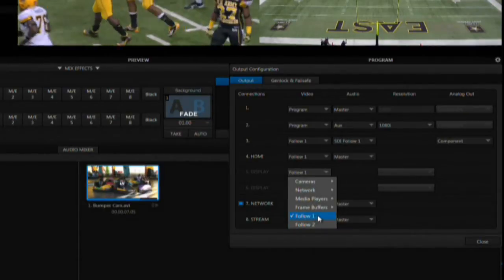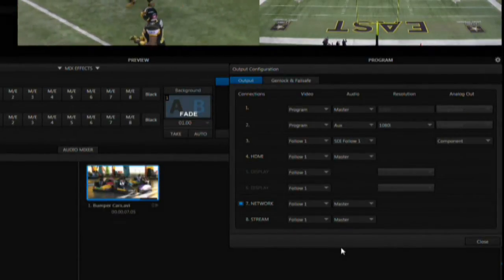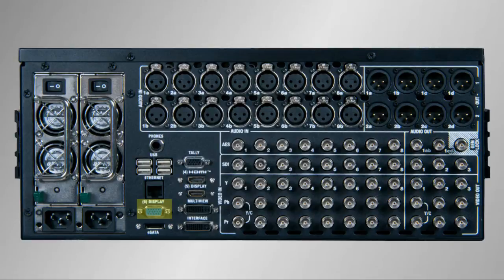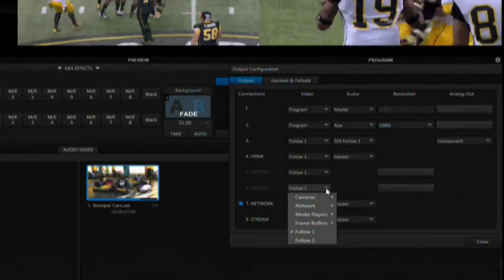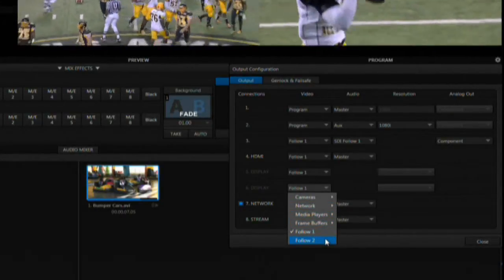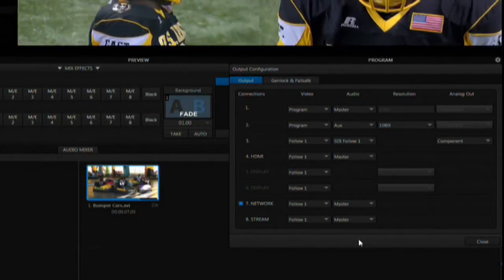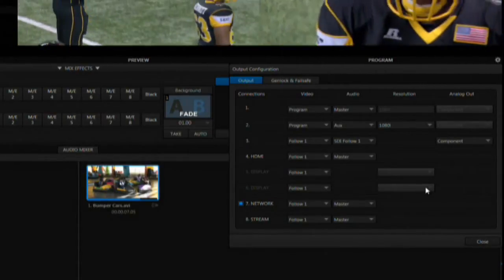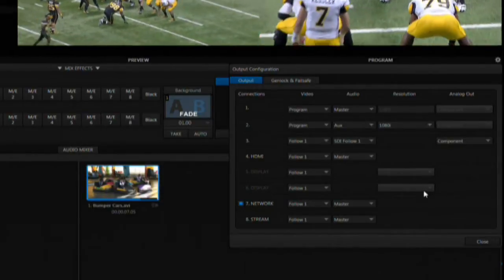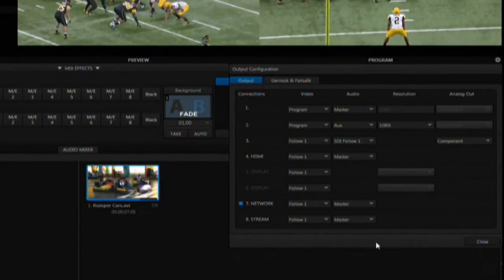You can also set the resolution of this output using this pull down. This allows you to turn off the scaling in an external projector, which can reduce video latency. Output number 6 is the VGA connector, and it's another display output configurable in the same way as the HDMI display output number 5. You also have the ability to configure the resolution of this output to match the resolution of, say, a projector, allowing you to turn off the scaler in the projector for better real-time performance.